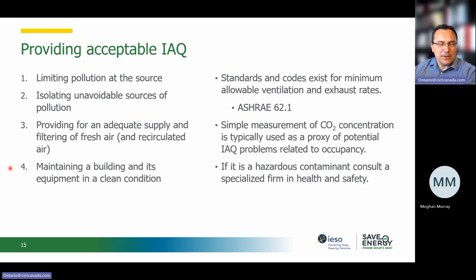For example, a simple measurement of CO2 content in the return air will give us an indirect feedback on the air quality factor in an occupied space in most commercial, institutional, residential buildings, and some industrial buildings as well, CO2 being an indirect indicator of occupancy, the number of people that we have in the space.